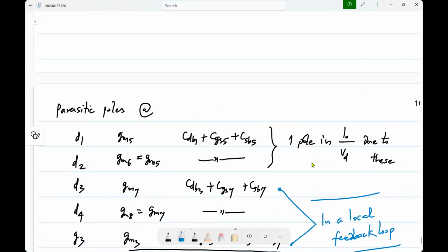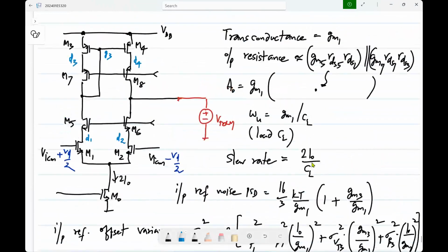So that is basically it about this type of cascode op-amp. We will discuss another type. Here, for the NMOS differential pair, we used NMOS transistors as common gate, but that's not necessary. We can use PMOS common gate for NMOS. Similarly, here for the PMOS current mirror we use PMOS cascode, and that can also be inverted if required. So we will discuss the other type of cascode.